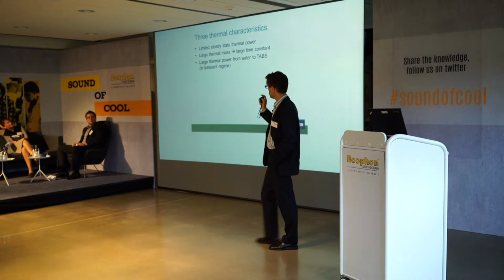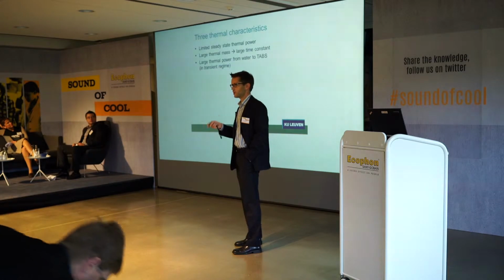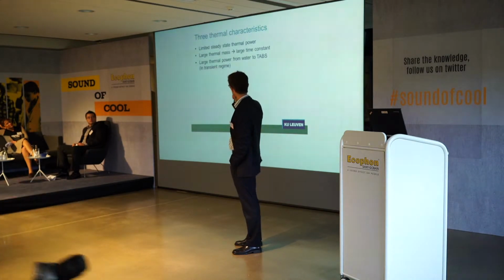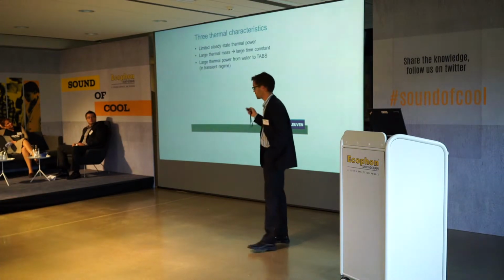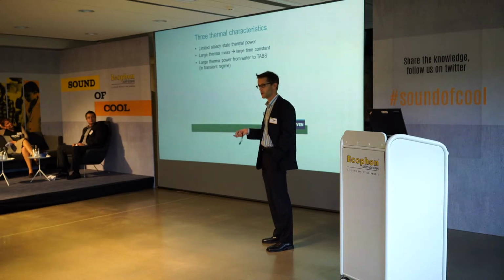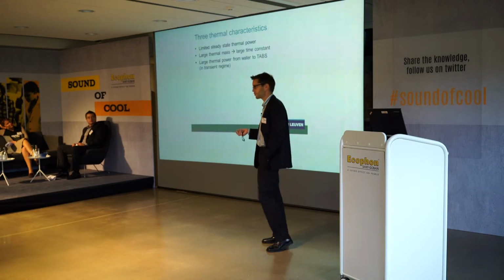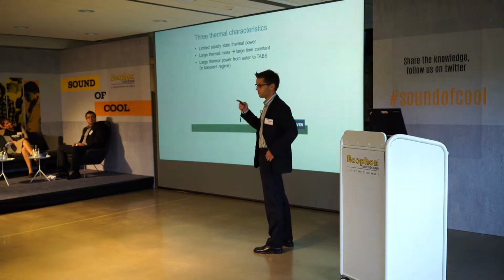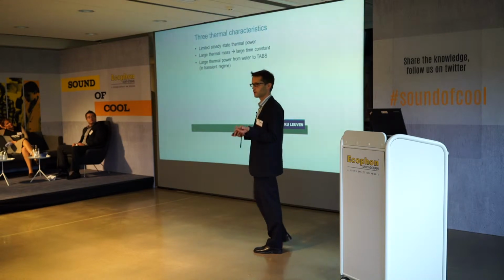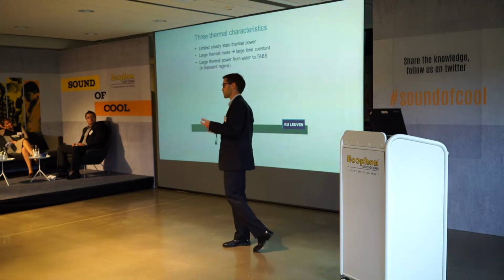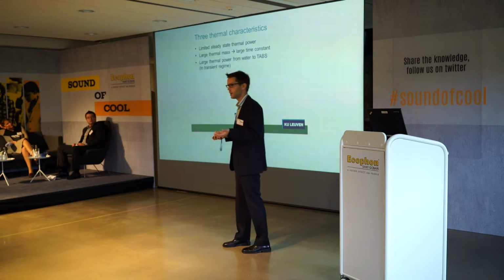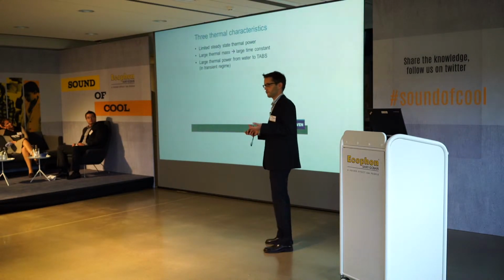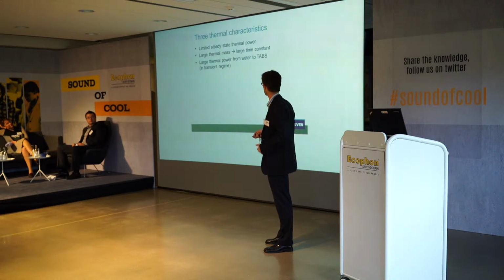When designing a system with TABS, you should take care that there are three important thermal characteristics. First, it doesn't have that much power. Yeah, you have to face it. The power is limited. You have to take care by making a building which doesn't require so much power. If you're installing TABS in a building that requires more power than the TABS can deliver, well, from the control point of view, you don't have a system that can work, because it's not able to deliver the power that's required.